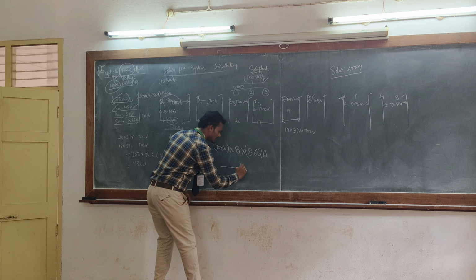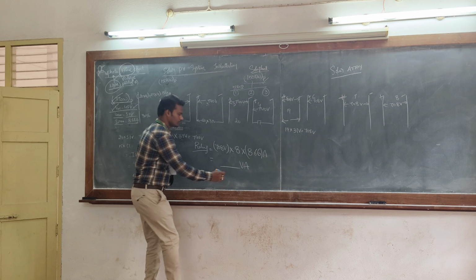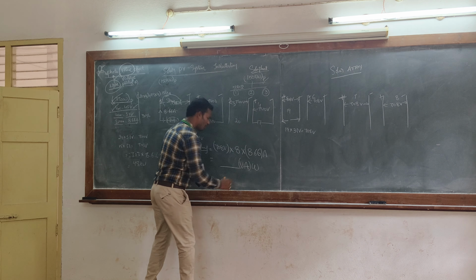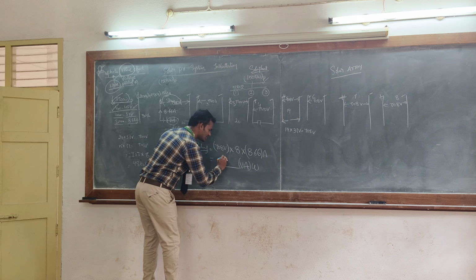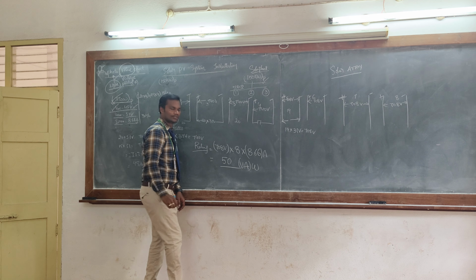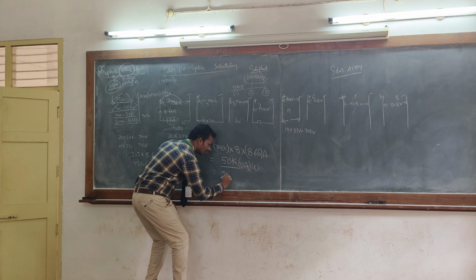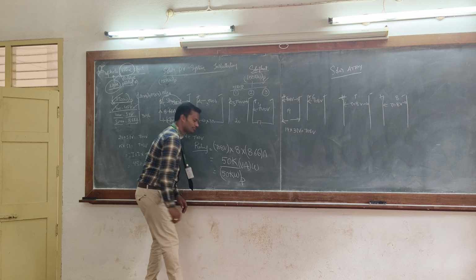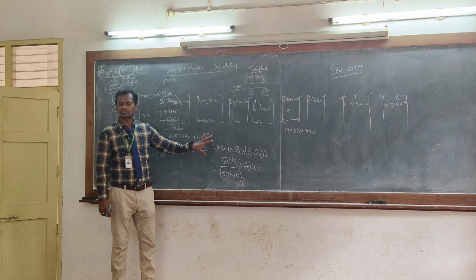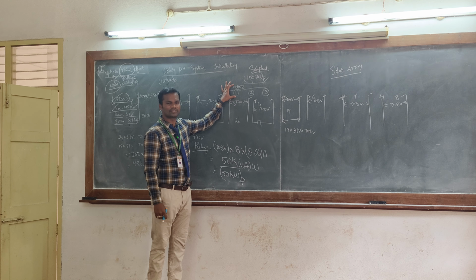Automatically you will get the ratings in terms of volt ampere. It's nothing but watts. How much? Okay, 48. Approximately you take it as 50. So 50 K. You are going to get resultantly 50 kilowatt peak. Now successfully we constructed the first group of panels with 50 kilowatt peak.